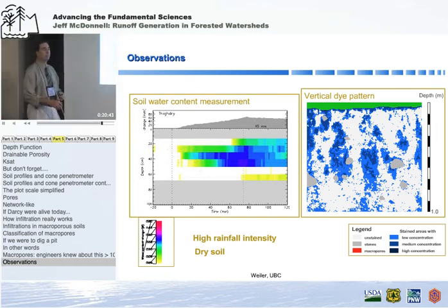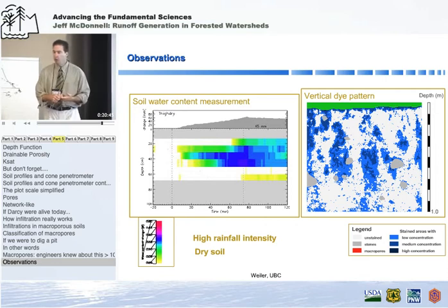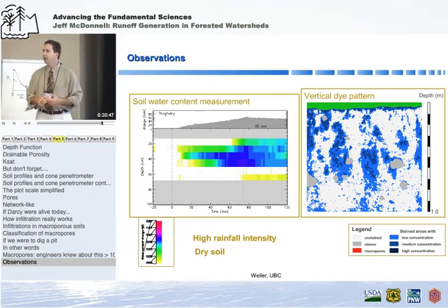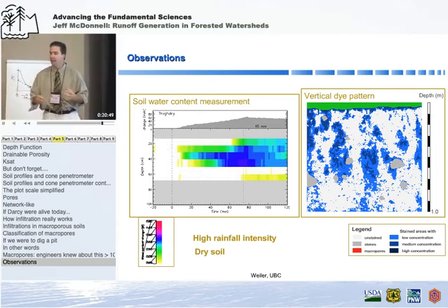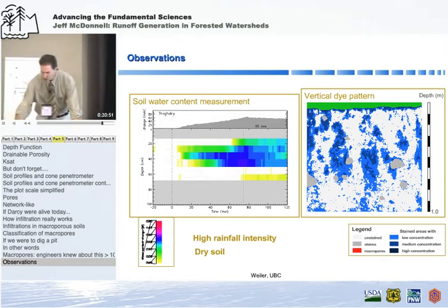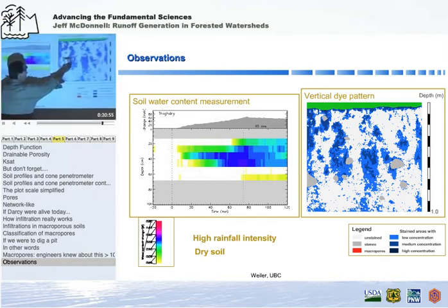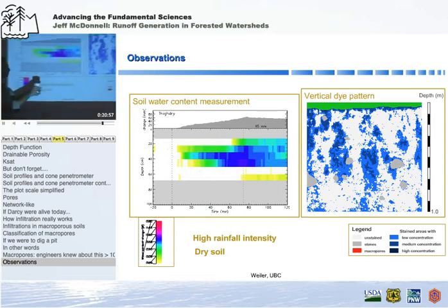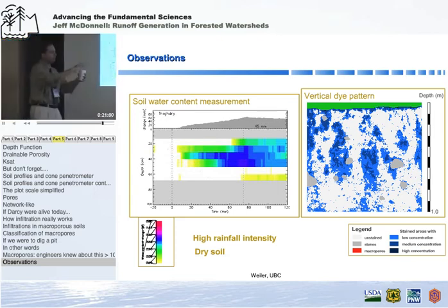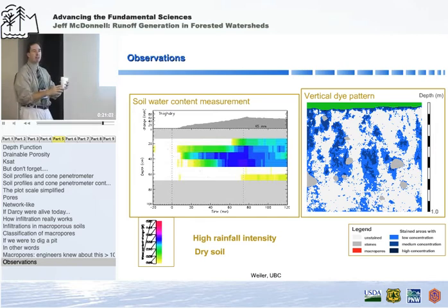This is the representative elementary volume concept personified, meaning that if this was our soil core and we extracted it from anywhere in the profile, we would say that this volume is not capturing the full range of behavior of that environment. This isn't representative of the continuum of pore size characteristics in this soil setting.